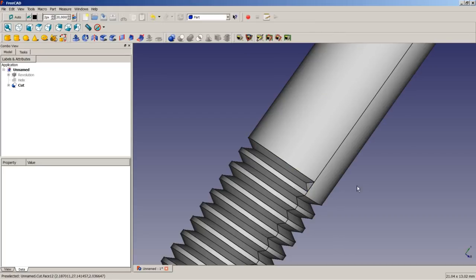But as you will see, FreeCAD basically can do helix operations, but its main geometric core is very weak on such operations. We will have to cheat to achieve the correct result with these operations, at least with the 0.15 stable release on Windows 7 64-bit.